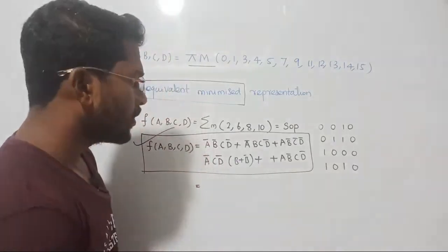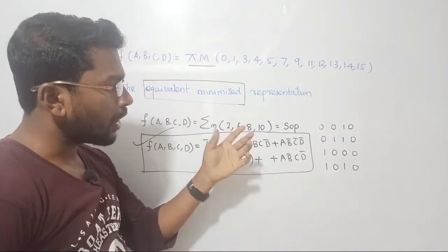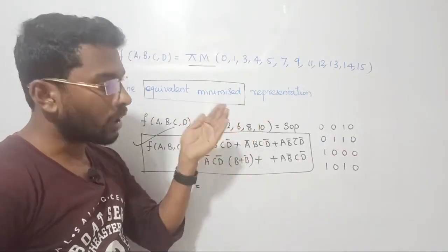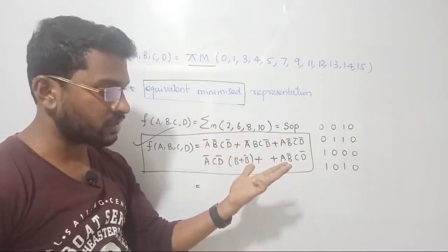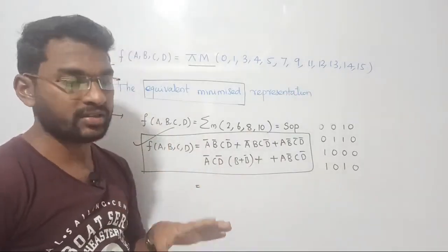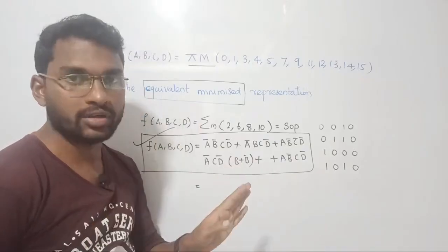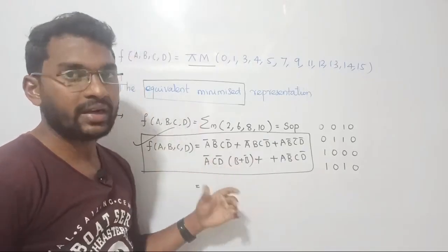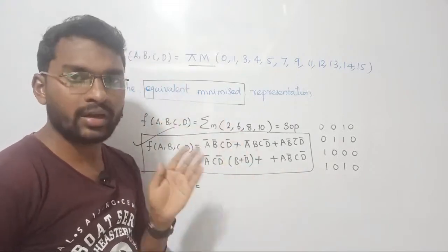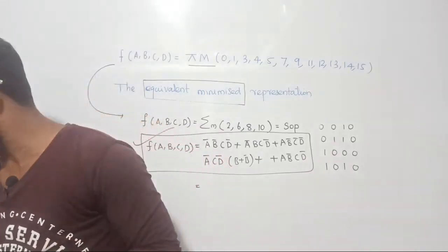Strictly follow this. I told you 2 conversions. Now you know how to write the equivalent expression from SOP to POS and POS to SOP. And you also know how to write the standard expression for max term and min term separately. Don't mingle them while solving the problem. That's my sincere request. There are some other procedures, but don't follow them. The methods that I taught are more than sufficient. You can proceed without any doubts or hesitations. Definitely you'll get the answer, trust me.